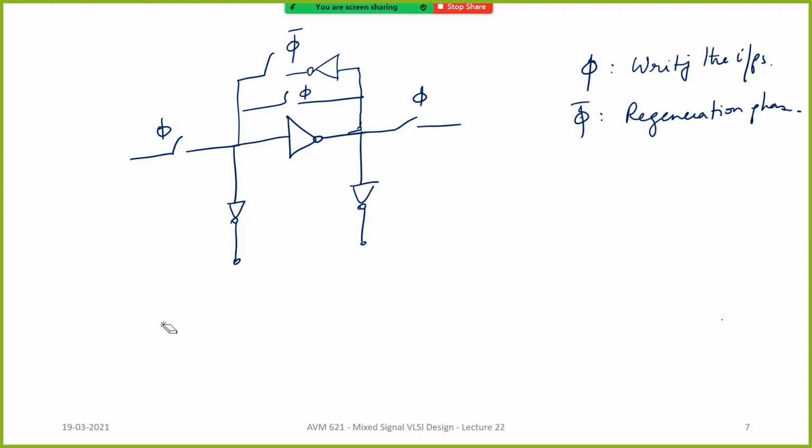So in sense amplifiers, you basically use something very similar. The peripheral circuitry around it will keep changing from implementation to implementation. But pretty much, if you look at clock comparators, at the heart of it you have cross-coupled inverters. And the strongARM latch is something that is very widely used. We'll see what are the small things available around it.